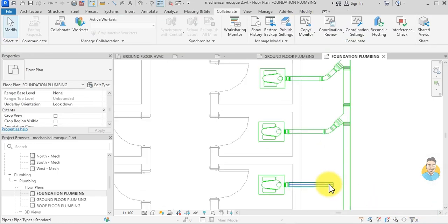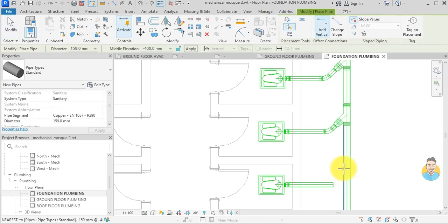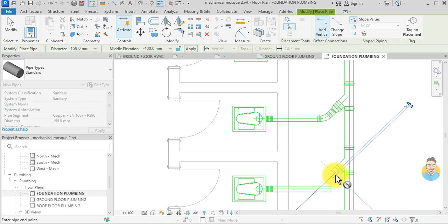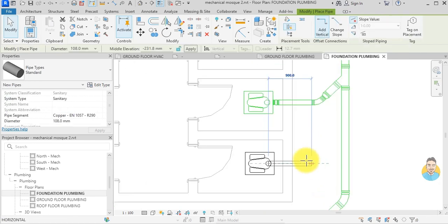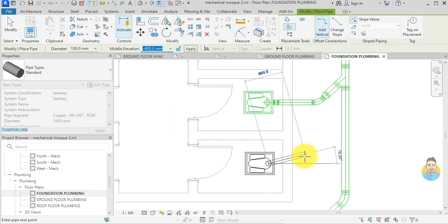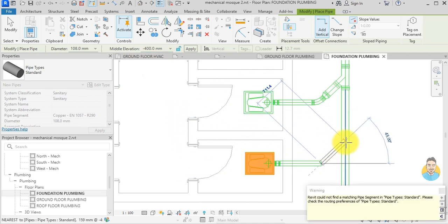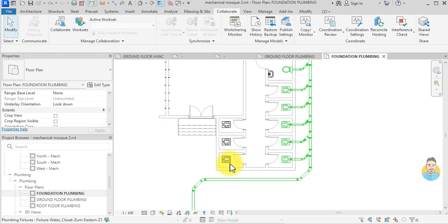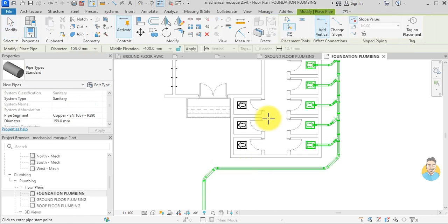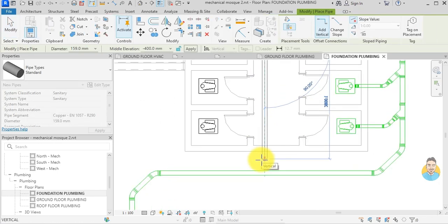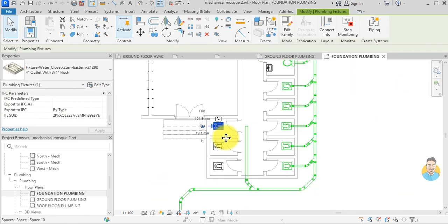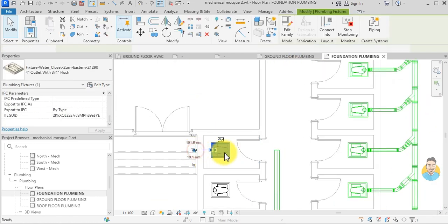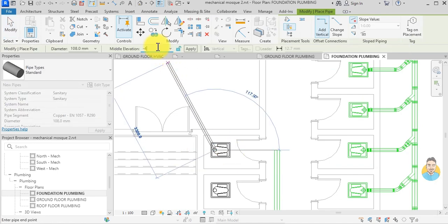Sometimes if it acts like that, I can also go to this pipe, CS, and start from here and one click, and then TR for trim, and I trim it. Click here, minus 400, click here and click here. And then CS to create similar. I can just get all these ones connected to the 6-inch pipe and connected back to the minus 400.